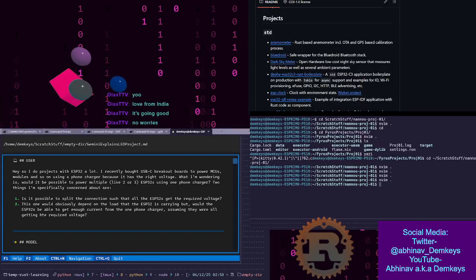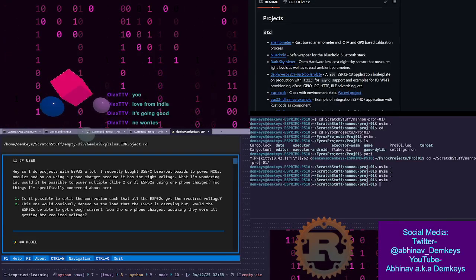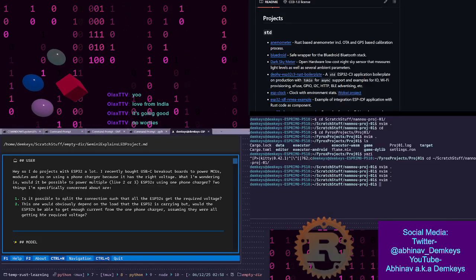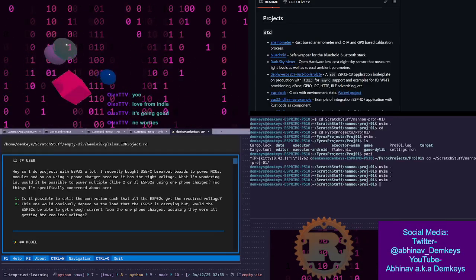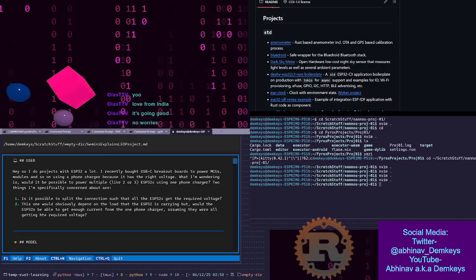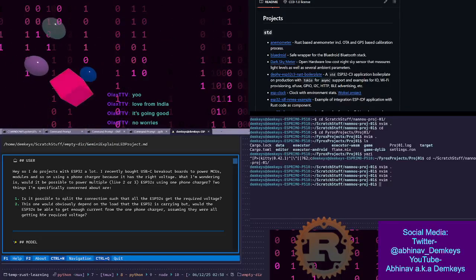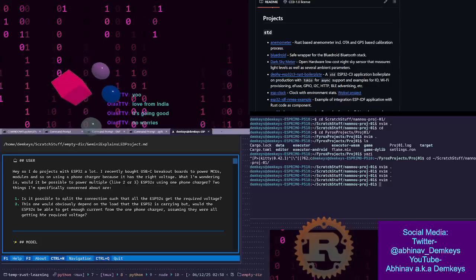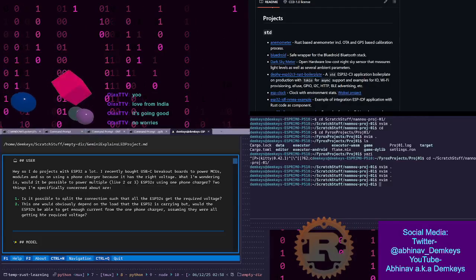They give you 12 volts, 5 volts, and 3.3 volts. So I can use the 5 volt wires, and I think they give you anywhere between 2 to 5 or 2 to 10 amps worth of current.